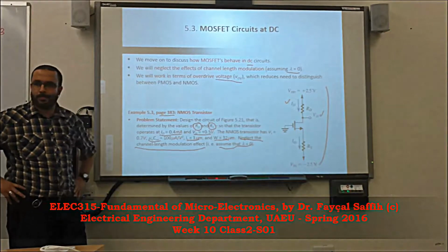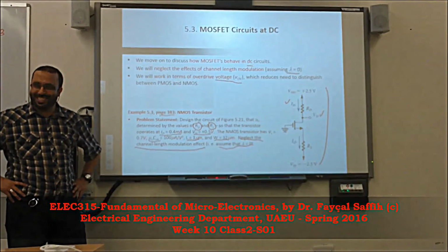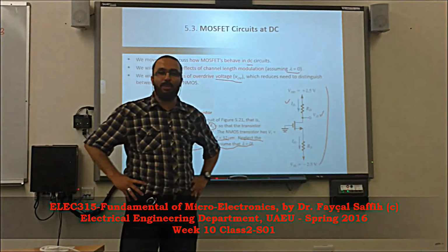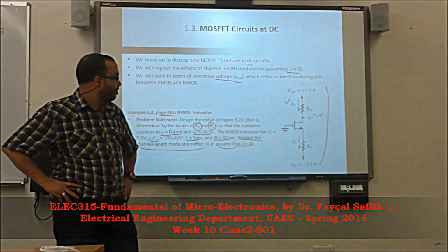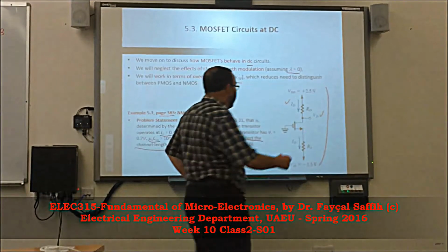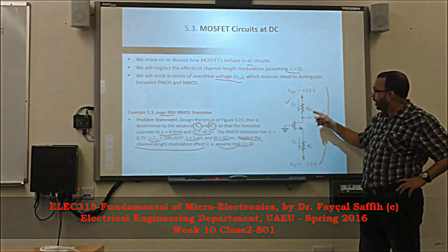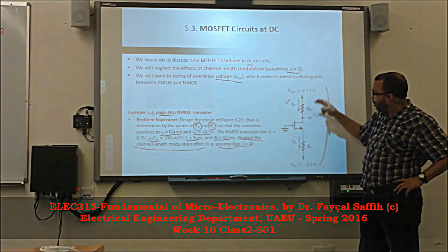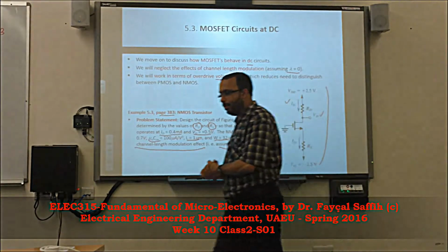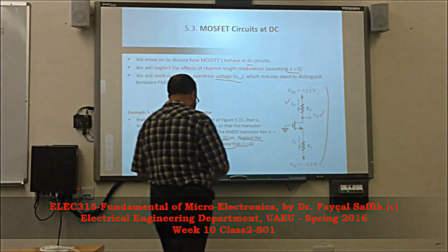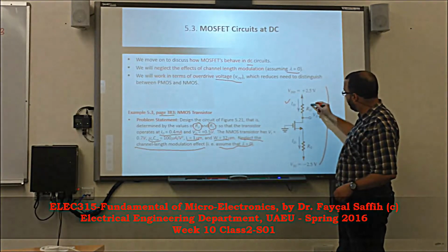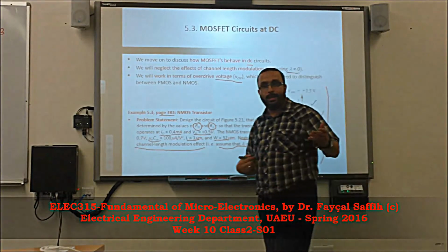What do you think, without looking at the textbook? Yeah, VDD minus VD. Nice try. Yes. VDD minus VD over RD equals ID. So the first, very good. RD is very simple, because we know this voltage, we know this. This minus this divided by that gives us RD. We call this a straightforward solution. So now RD becomes, check. Now RS.